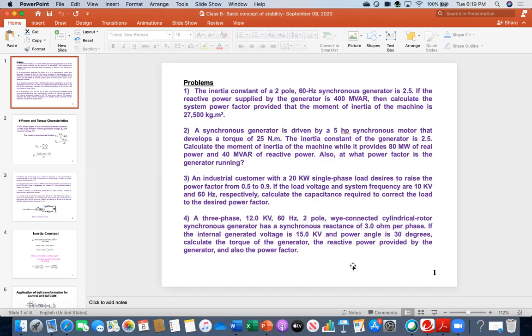So you got the power value 30 megawatt, right? Yes, Dr. Ali. So then you just need to divide that number by the omega in radian per second. Therefore, you see the problem, the very first line, 60 hertz. From there, you calculate the synchronous speed first, 120 f over p.